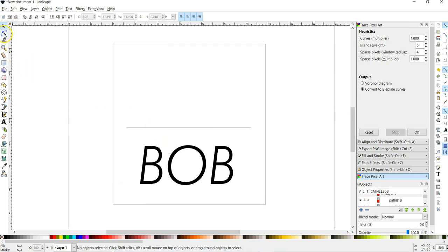Moving on here, we have this thing called a vector editing tool. It's a tool that helps us edit vectors, strangely enough, as it's called. And you'll notice that if it's a vector, it's going to start to light up in red first, and when you click it, it has nodes placed on it. However, if I do that with the text, there are no nodes. And what you need to understand going into this is that for the plasma cutter, or for our table to cut any design, it needs to be a vector, whether it's a CAD or DXF based vector, or if it's an SVG vector. We need vectors.